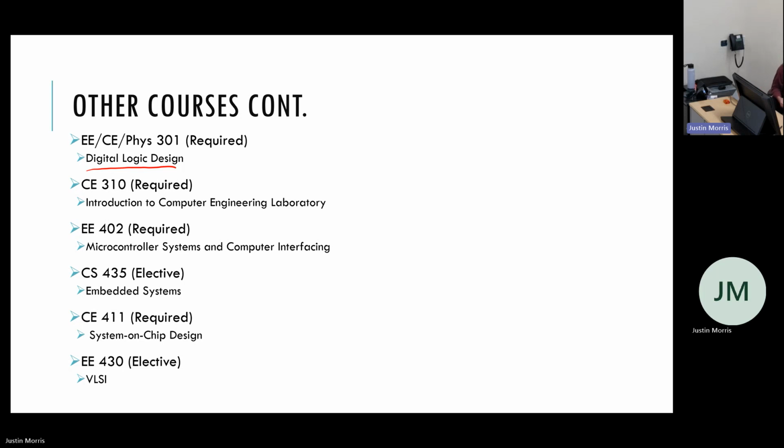Question about when you were talking about FPGA, is that the same as VHDL? So VHDL is a hardware design language. There are other hardware design languages, just like there are other programming languages, but they all just get translated ultimately to the schematic design that gets burned onto the FPGA.